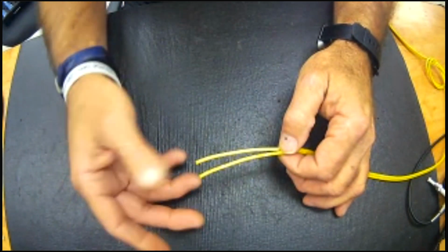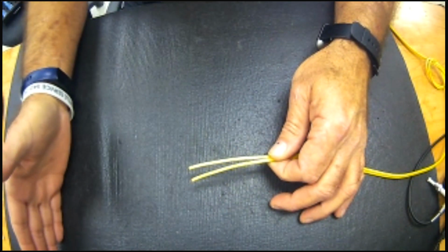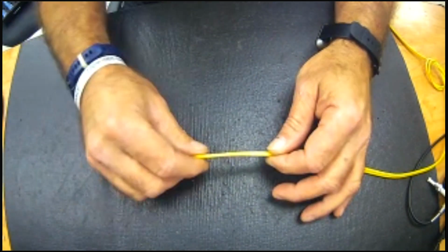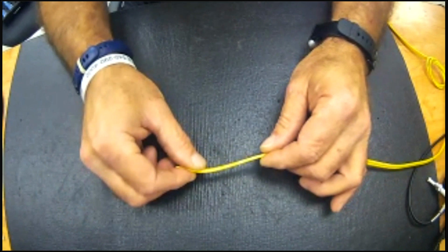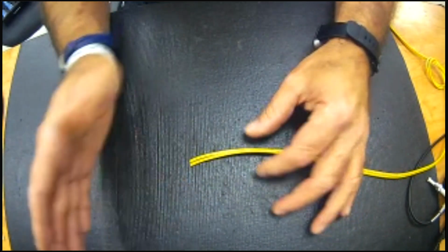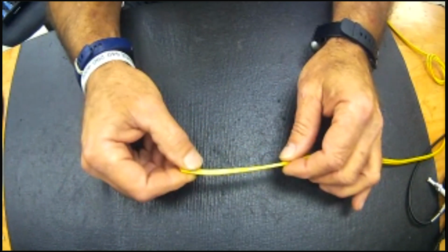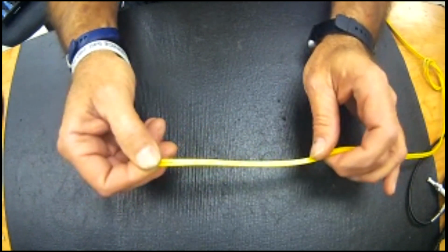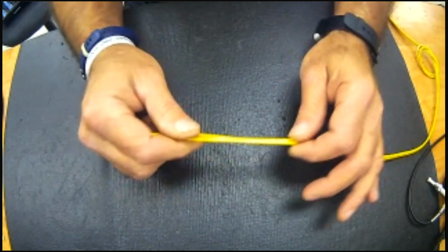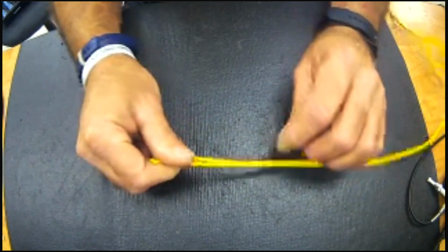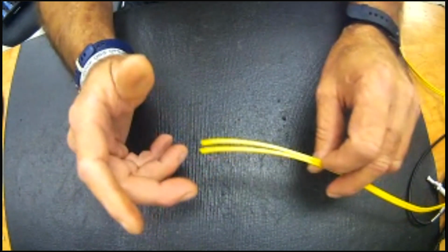In the single mode world, there's really only one flavor. In the multi-mode world, we've evolved into different flavors, but OM3 on, you're going to be okay. OM1 was the only crazy one in the transition, and OM2 was a little crazy. That was 62.5, but we're pretty much strictly 50 micron. 9 micron being our single mode, and broadcast is predominantly single mode. I would never design around multi-mode. I don't suggest you either. It'll get you in trouble. The other thing I'd like to talk about is connectors.